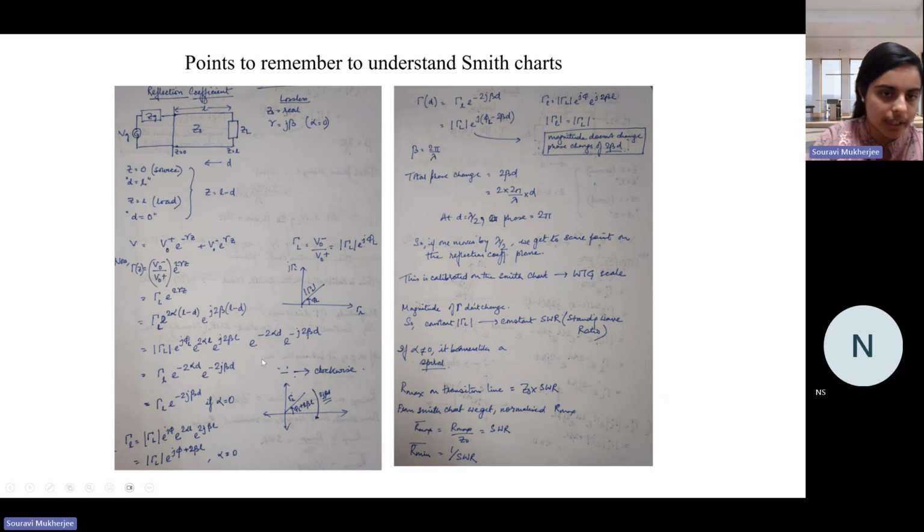So suppose now if you put alpha equal to 0, you would get something like this, where here you have this small l, so gamma small l, this includes all these terms. And again, if you put alpha equal to 0, you would get something like this. E to the power 2 j beta L is not very important because it doesn't add anything to the amplitude. It's just a phase. So if you find the modulus, it would turn out to be the same.